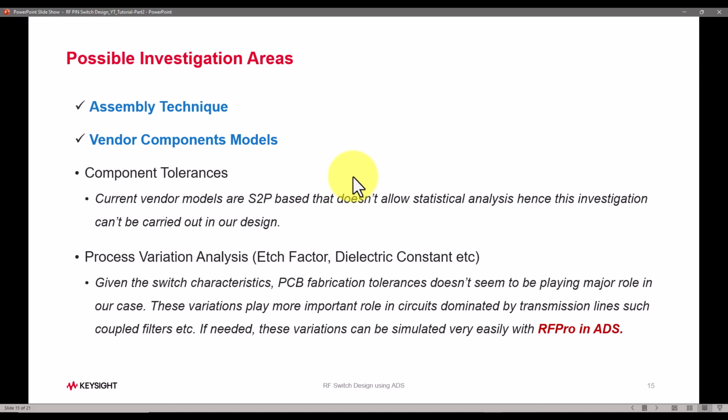When you are in this kind of design process where you need more flexible control on your discrete components such as inductor, capacitor, try to use regular discrete models, but make sure you account for Q factor in each of those models, especially if you're dealing with resonant circuits like filters or using those components in impedance matching applications. Those components will allow you to do a lot of Monte Carlo yield analysis and such.